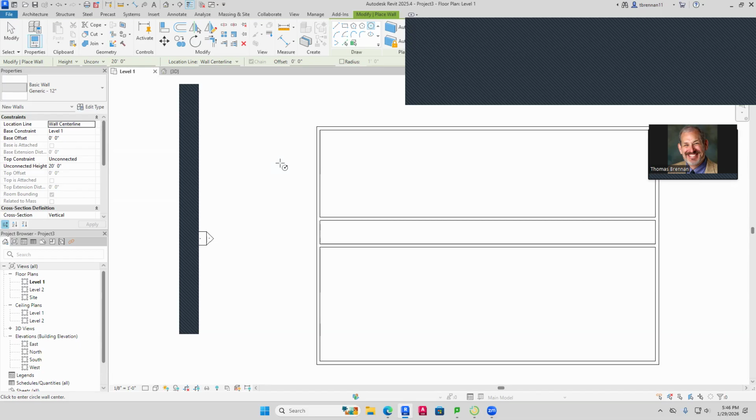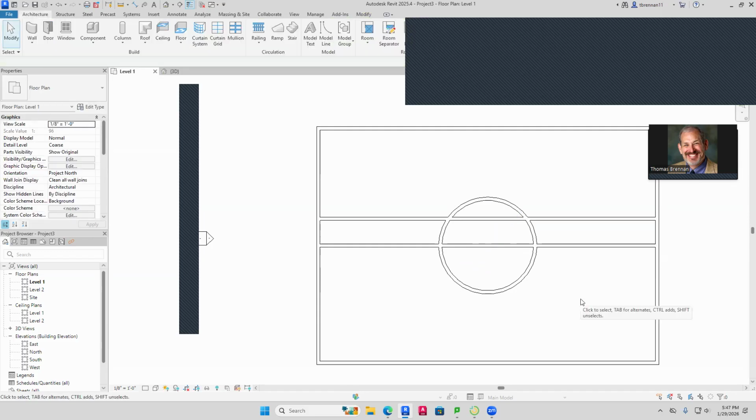And so now we're going to pick this location here. You want to take it and put it on this mid wall right here. Now see this right here? If I keep on pulling this along, I find this midpoint there. So I'm going to click right there on this triangle. I'm going to pull it down until I see it say 14. Once it says 14, I'm going to click. And then it gives me this, and it actually cuts out the walls. Press your escape key twice.